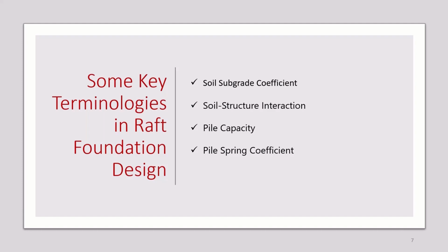It is used in determining the rigidity of the springs used for modeling the soil behavior. Basically, you can call it the spring stiffness, which is in kilonewton per meter square of ground. The coefficient of subgrade reaction is measured and expressed as load intensity per unit of displacement. So either way you want to define it, understand it, please, I will encourage you to check this out.